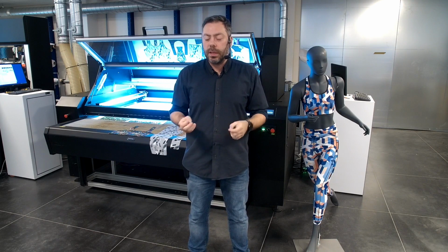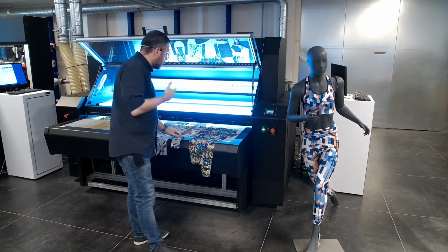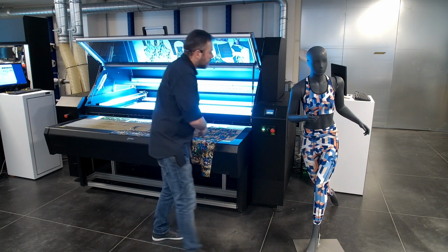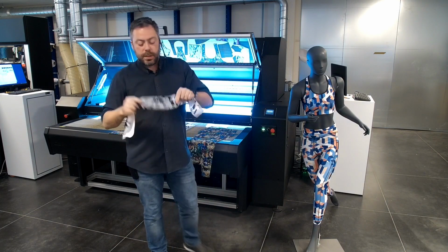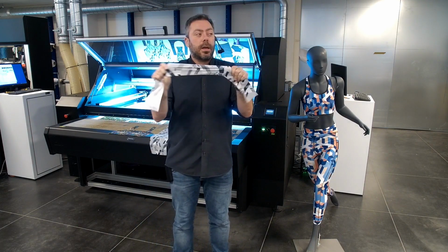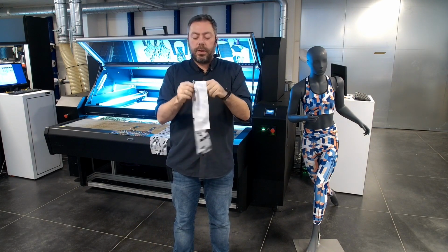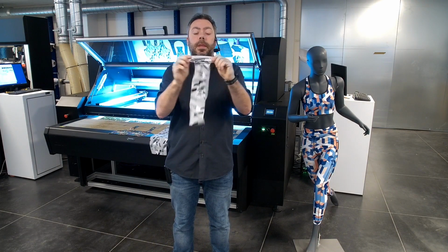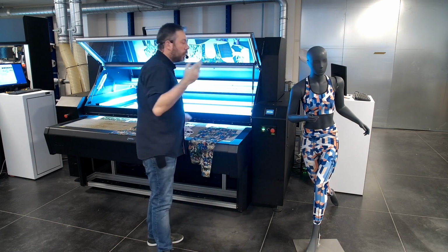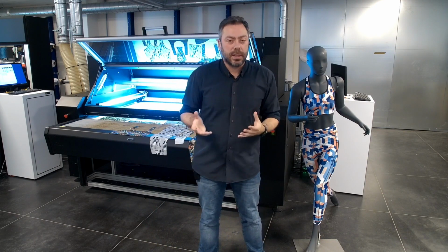With the laser, because laser is non-contact cutting, it generally moves the fabric, and while it's moving, it's able to cut it without moving the fabric around. So there is no interaction on the fabric. That leaves us also the possibility of, let me just grab this. If you look at this fabric, it is quite stretchy in a lot of directions. So if you use a knife, you're going to stretch that fabric while you're cutting. With a laser, that doesn't happen.